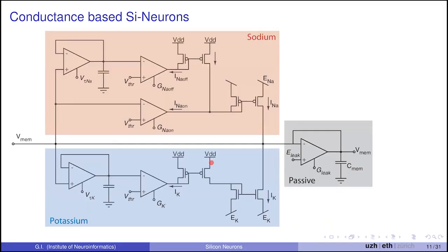And so what dominates the area in these circuits is always the capacitance. You might be able to make these transistors really tiny, nanometers or micrometers, but capacitors will take up hundreds of square micrometers. So it's still not scalable. In order to put 1,000,000 neurons on a chip, you would require a very large area, like centimeters square, or even more, on a single die.